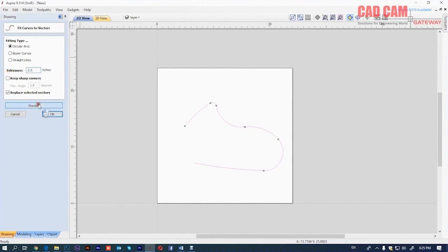So it depends on what kind of radius you are giving it, and when setting the radius, keep in mind how large your working area is and what the gap is between one point of the line and the other. It shouldn't be the case that there's a 1 inch gap between your 2 lines, but you're setting the tolerance to 5 inches. If the gap between one line and the other is 1 inch, then play around with 0.25. Set the tolerance to 0.25.